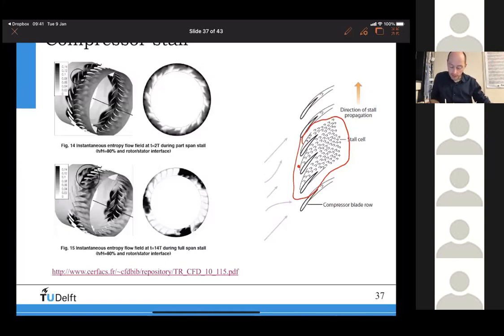Imagine this is the wing, and this is the gas turbine below it, an old one with a very low bypass ratio, or maybe not even a fan. Flow comes in here and has to go out here. Here you have the compressor stages, here the turbine stages, and this is the combustion chamber.